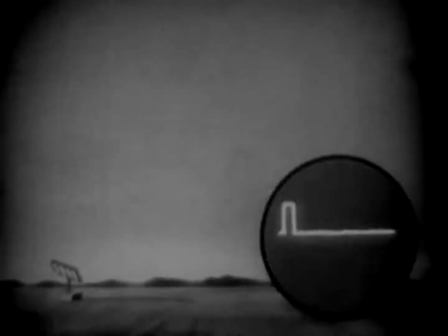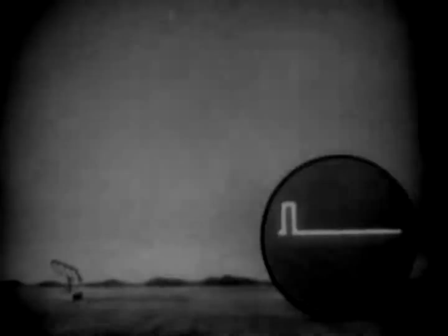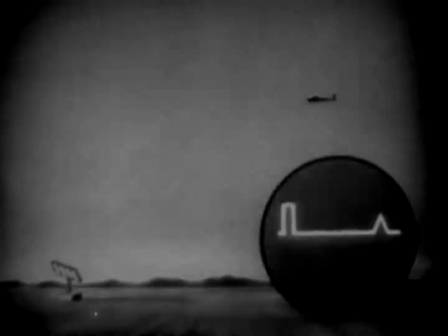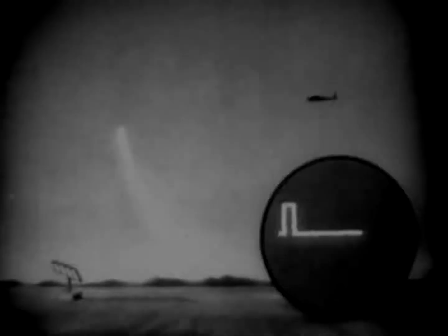The sweep of the baseline is synchronized with the outgoing pulse, so it can measure the time it takes a pulse to leave the transmitter, reach a target, and its echo return. When the outgoing pulse strikes a target and part of the energy is reflected back to the radar set as an echo, the receiving antenna's job is to pick up the returning echo and shoot it along to the sensitive receiver. Here, the weak echo is amplified and sent as a voltage pulse to the indicator,